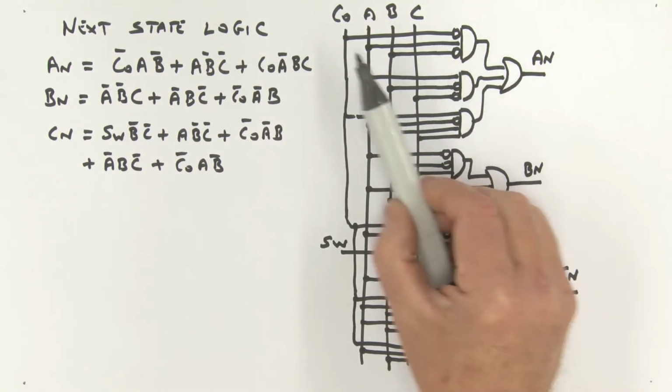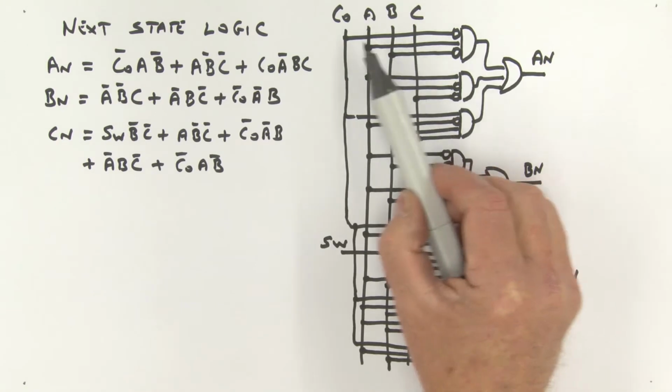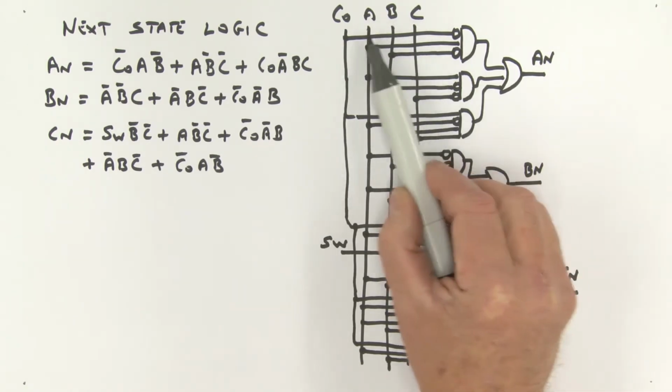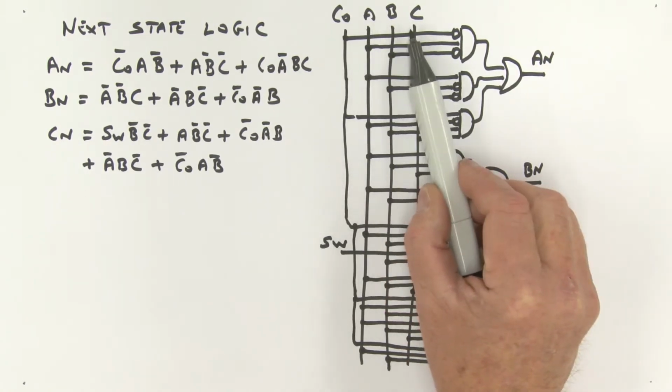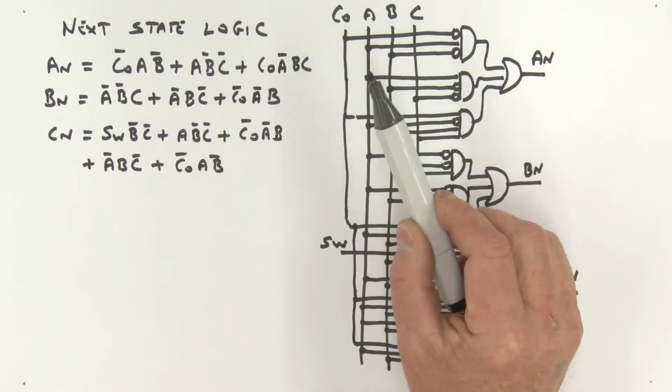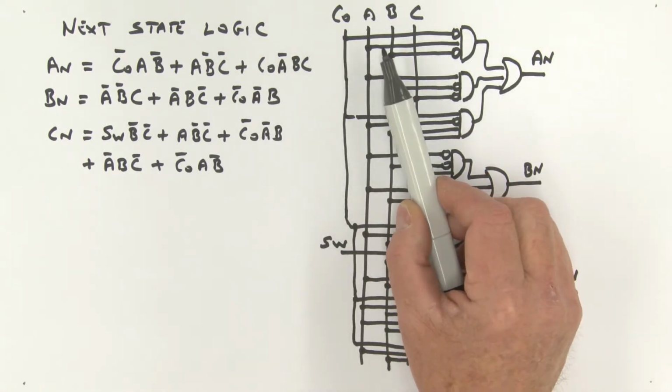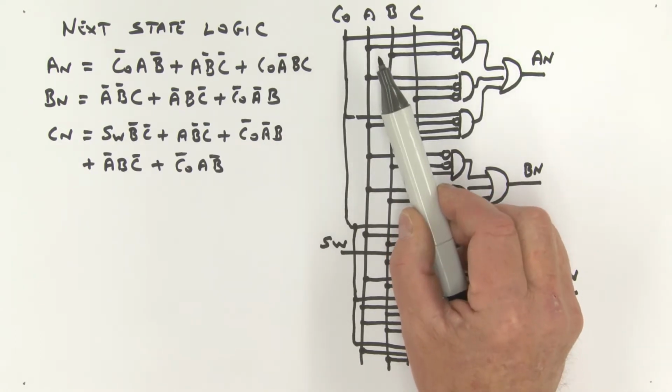Look, before I actually leave this diagram here, I just want to ask the question again, A, B, C, where are these guys actually coming from? Yeah, they're the outputs, are they not, of the state variable flip-flops. Now, you'll also note that those D-type flip-flops, they will have what? 2 outputs. They have a Q and a Q bar.